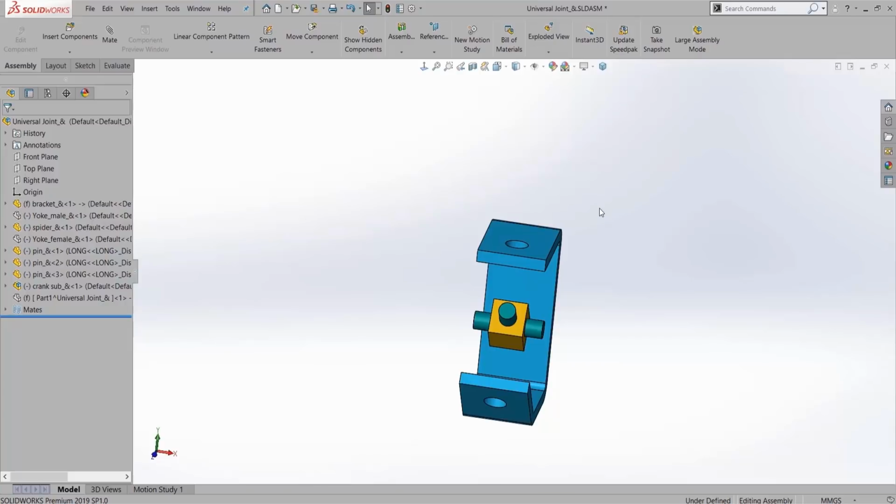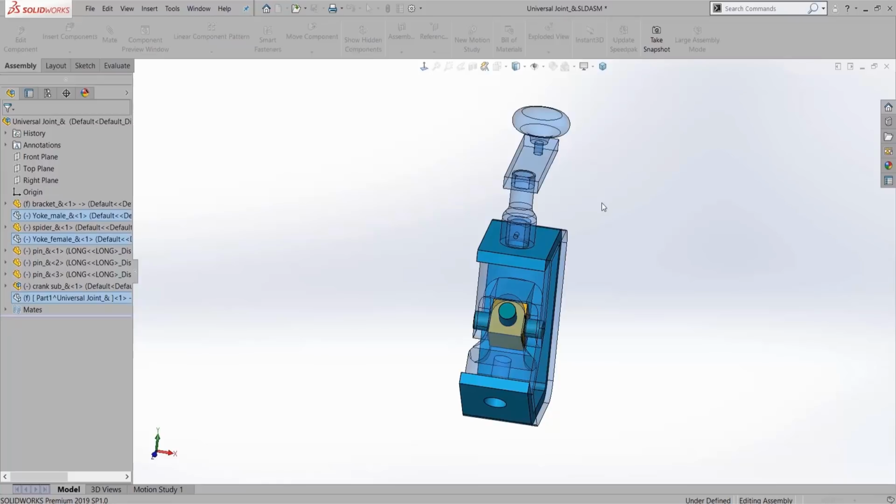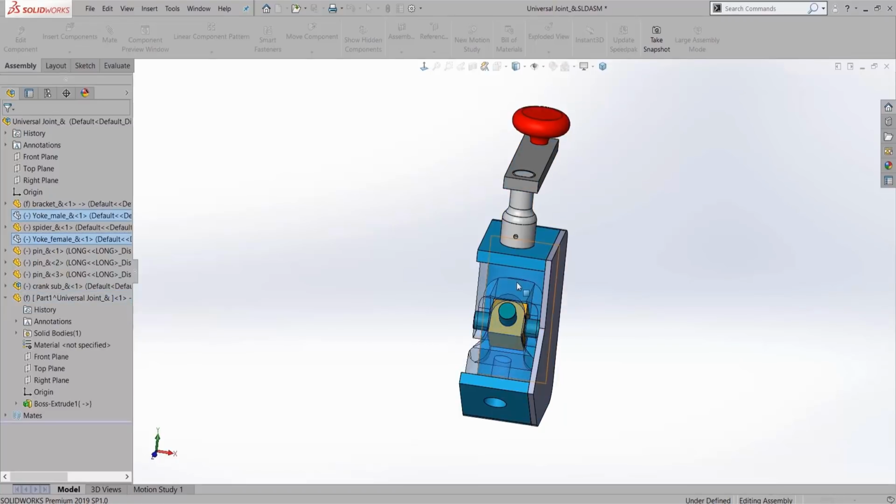Typically they're hidden. This can happen due to graphics card driver issues. So if I hold Control, Shift, and Tab at the same time, it makes everything that's hidden a translucent blue, and I can simply click on these parts while holding these 3 keys to make them visible again.